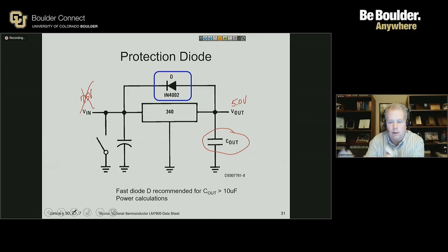And until there's enough drain to pull that charge off those capacitors and drain that voltage down to 0, you could have a scenario where the output voltage is higher than the input voltage to that regulator. And what you're trying to do is prevent large amounts of current flowing back through that regulator and damaging it.